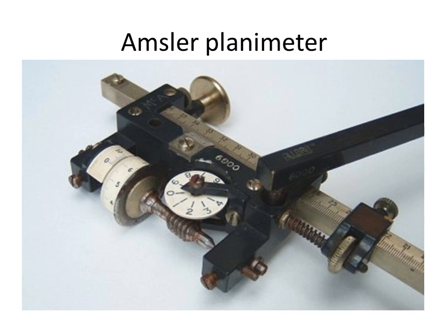So this is again the Amsler planimeter. Generally, whenever we are taking the reading, we are supposed to see this particular index, and depending upon the position where it lies, we pick up the lowest value. Since it is lying in between 9 and 0, we pick up the reading as 9. Then we consider this particular roller, and corresponding to 0 of the vernier, we pick up the 2 digits from the roller, that is 5 and 5.5. So 9, 5, 5, and then we consider which line of the vernier coincides with the main scale of the roller. Suppose it is 5, then the reading will be 9.555.